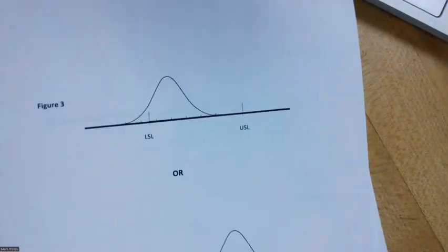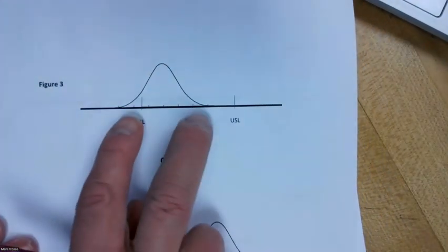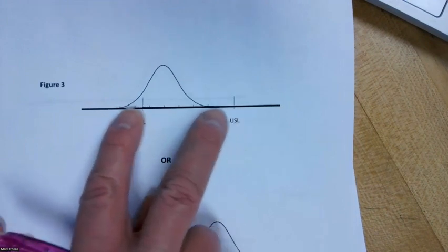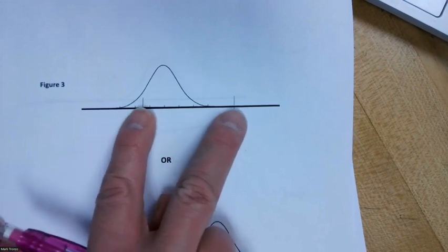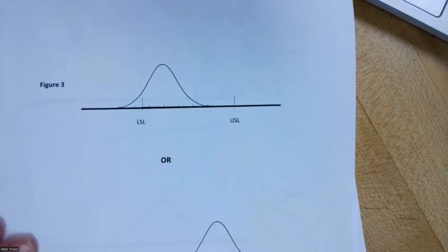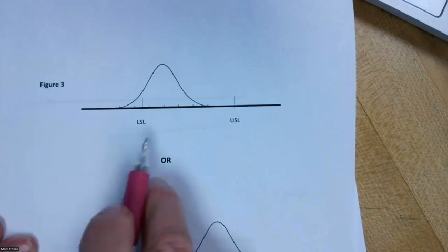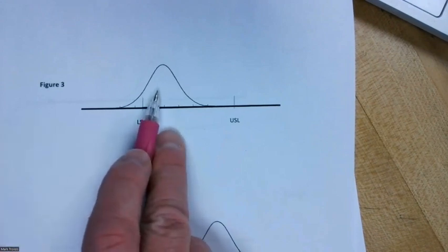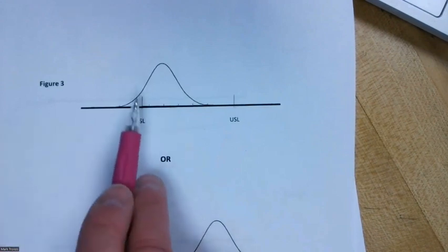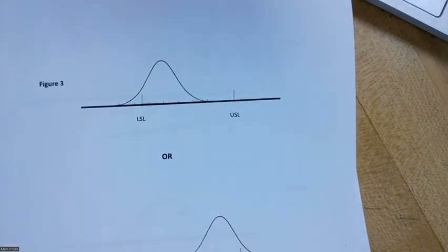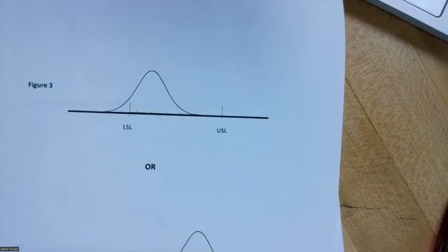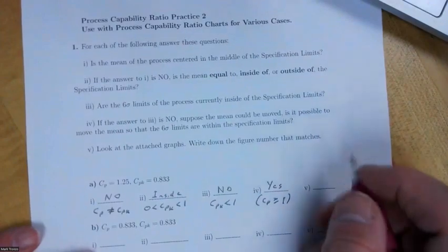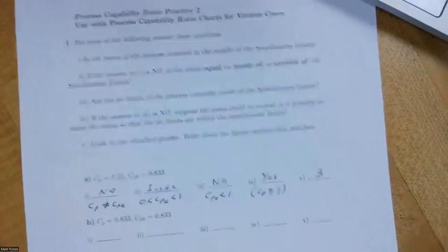You have the case where your CP value looks like it's bigger than 1, because if you could move this here, this could be within your specification limits. And yet CPK was between 0 and 1, which indicated the process mean was within the limits. So that's what you would go through to try to figure out where things are falling, if that makes sense. Is that the right answer.